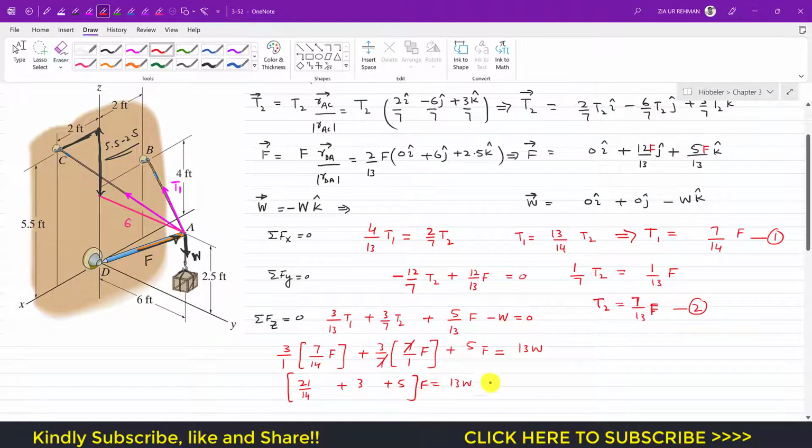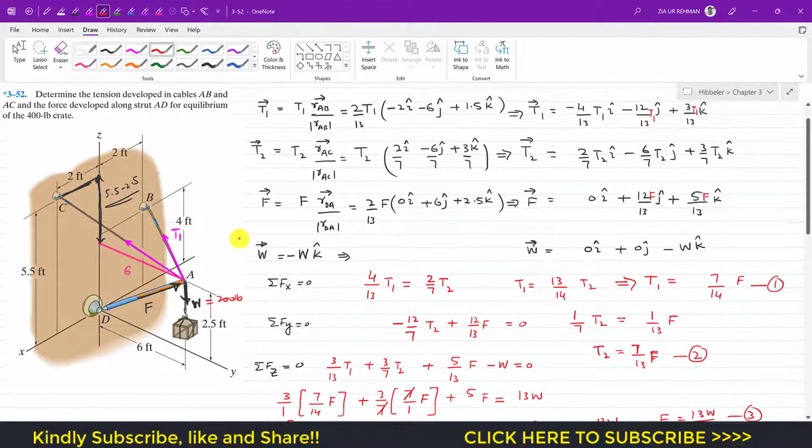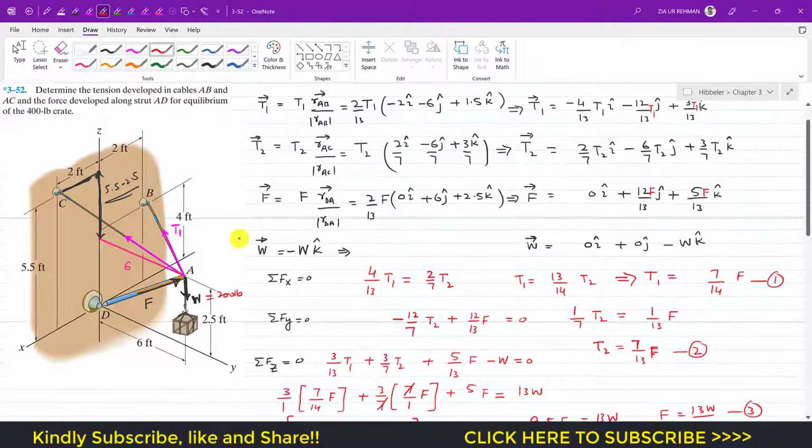So 9.5f equals 13w, or we can say that f is equal to 13w divided by 9.5. So this is equation 3. So now we have these 3 equations, and t1 is in terms of f, t2 is in terms of f, and f is in terms of w. And since the weight is given, if we know the weight, we can find t1, t2 and that force f.